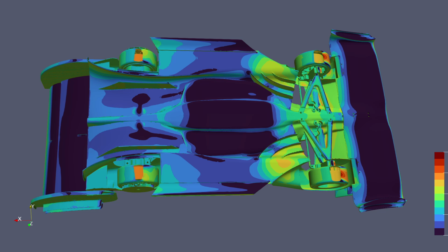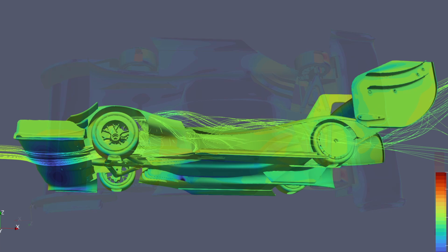And then it's just endless loops of optimizing and looking at the interactions between the various aero devices to try to eke out that performance and find little places you're finding flow separation, you're finding places where there's drag, you're finding aero devices that are not necessarily in the optimal placement for the airflow. So I did a lot of work around that, and I'll talk about those in more detail as we go through each of the aero devices individually.